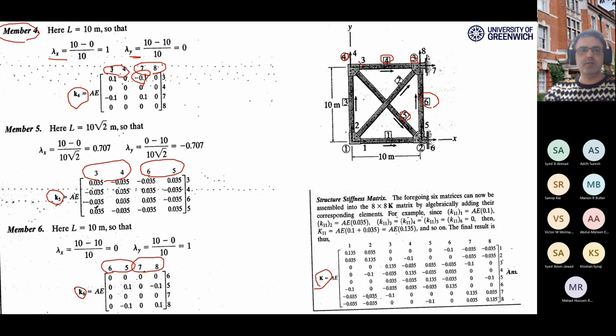It goes to the column 7 and row, this is column 7, this is row 3. So this is row 3 and this is column 7. This should go here, as you see. This number should go here. So you should repeat it for all the numbers in those 6 individual 4 by 4 matrices and put all of them into the right places in the bigger 8 by 8 matrix.